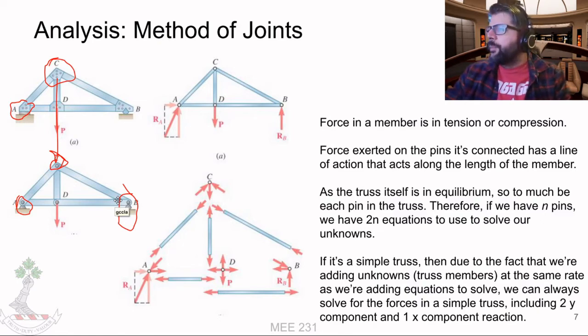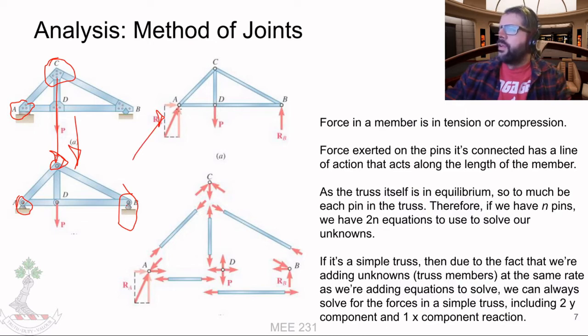But anyways, yeah. So move down to simplifying our supports and our connections. Draw a free body diagram of the overall structure. That allows us to get our reactions, and then from there we can draw free body diagrams for all of the joints, and that can be used to solve the forces in the members.